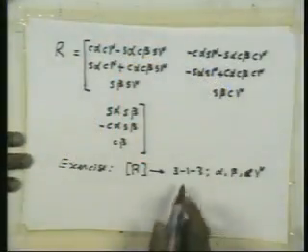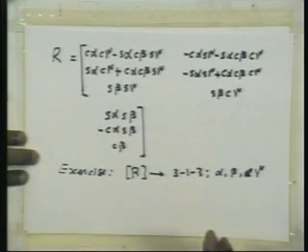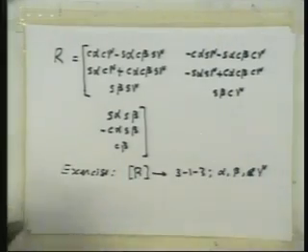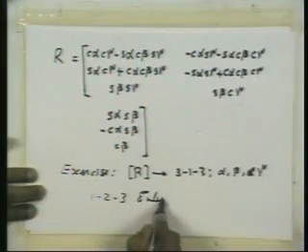Now I mentioned 313. Are there any other possibilities? Yes. Euler angles really mean this idea of rotating with respect to the local coordinate frame. Every time you shift the local coordinate frame, you rotate with respect to the current local coordinate frame axis. That is the idea Euler used. So you could have, say, 1, 2, 3 Euler angles.